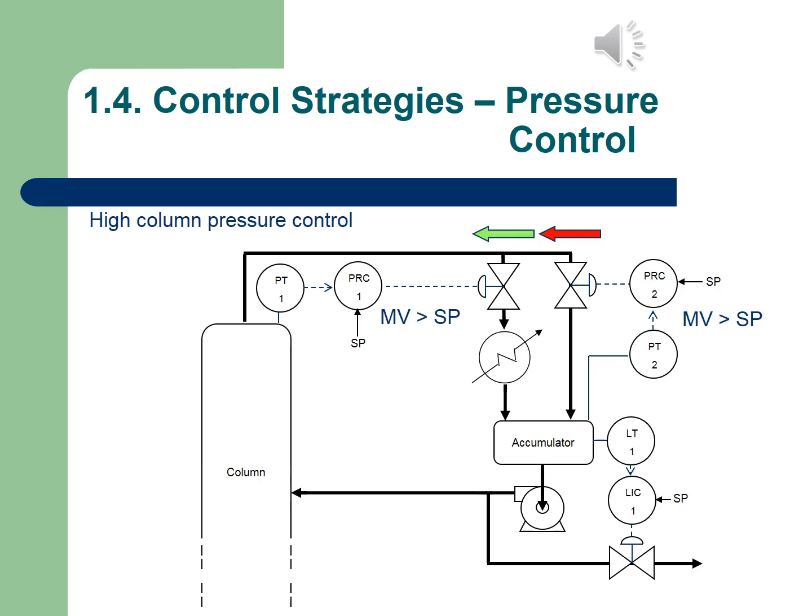Okay, here you will see under normal operation, just to get pressure released from the column, the first leg that goes through the heat exchanger will be opened, and just normal condensation will take place. Here you can see that both the two valves will be open, so it means that the pressure inside the column is high, and also in the accumulator the pressure is not too high, so we can quickly release some pressure into the accumulator, and condensing will then just take place in the accumulator.